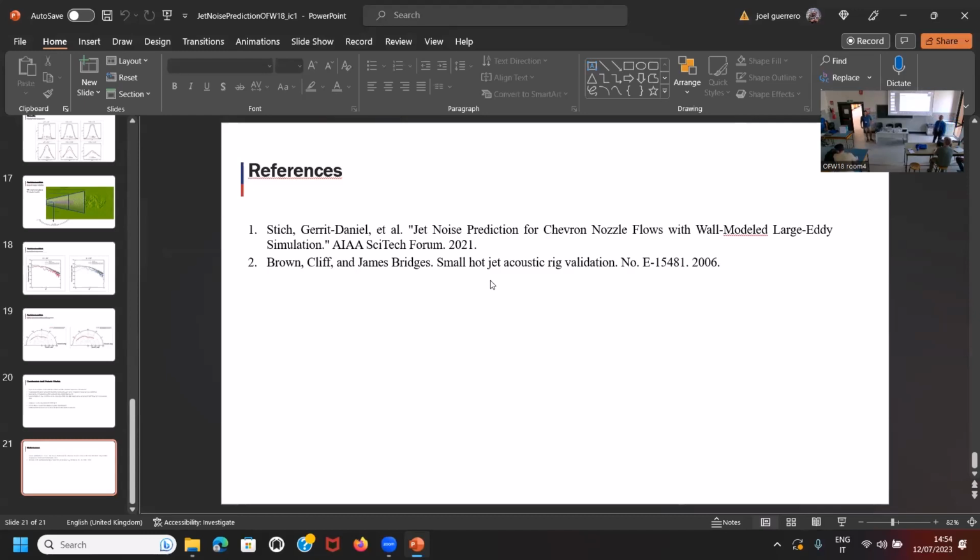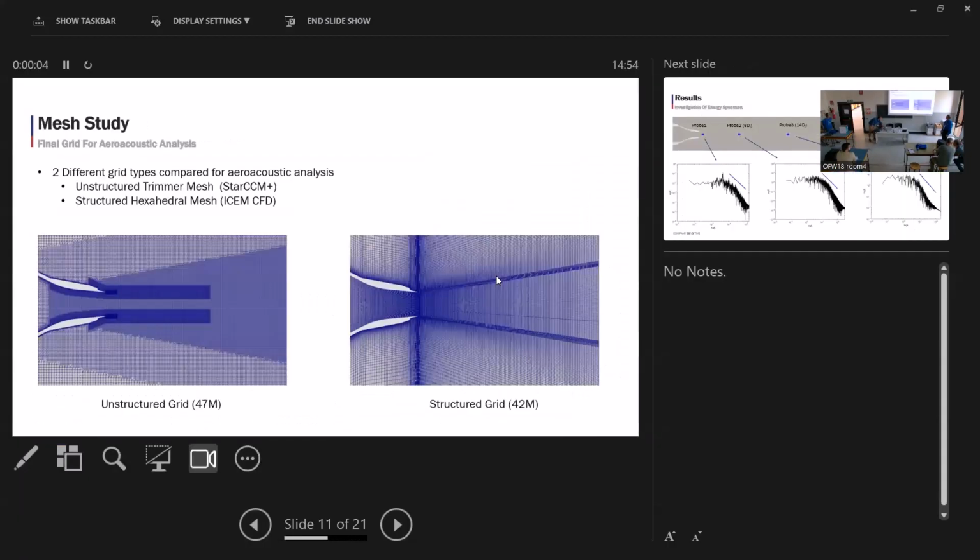You can highlight this line with the unstructured and structured. This one? Yes. So, in terms of scaling resolving situations, aspect ratios, you need to get a low aspect ratio. So, I'm a huge fan of structured grids. The case is that maybe the reason you get better resolution of the turbulent simulation on unstructured is not because it's unstructured, but because it's a low aspect ratio. When you get many high aspect ratio cells in the region of interest with structured grids, because that's how structured grids are usually made. So did you do a comparison of what is the aspect ratio of your structured grid?